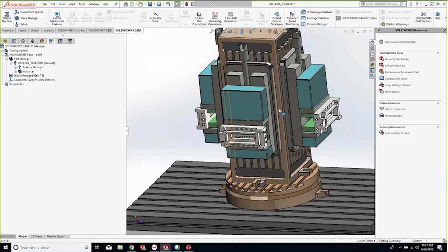It's just another kind of, I call them sanity checks, right? To make sure that Toolpath simulation looked good, the backplotter and the NC editor looked good. Now I want to make sure, just to triple check myself before I go out there and smash a tool or scrap a workpiece.